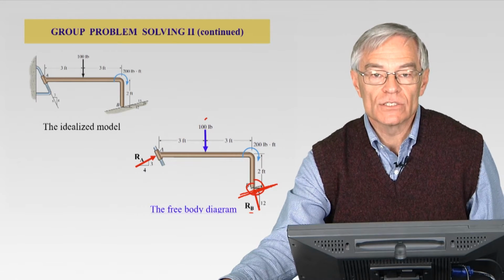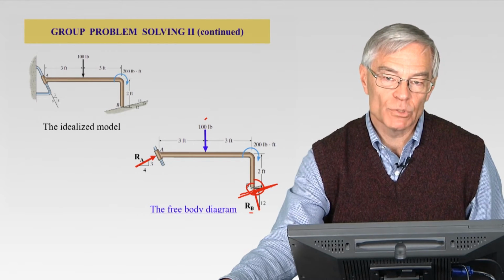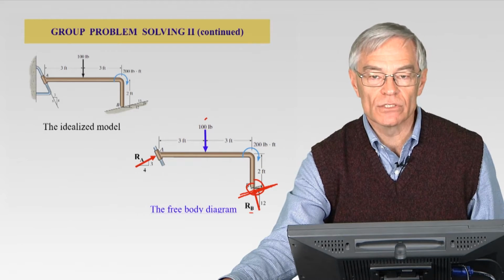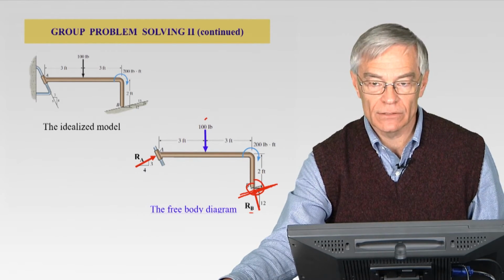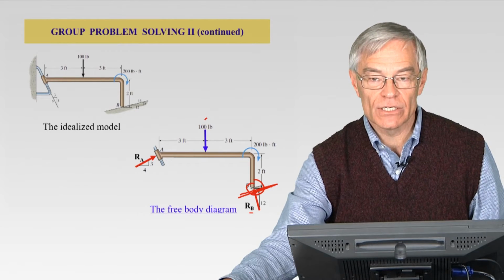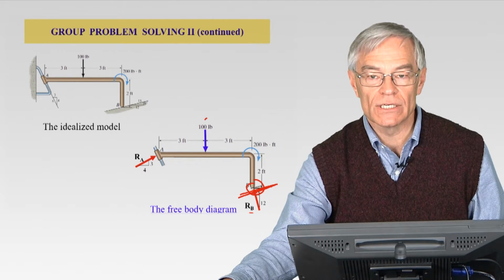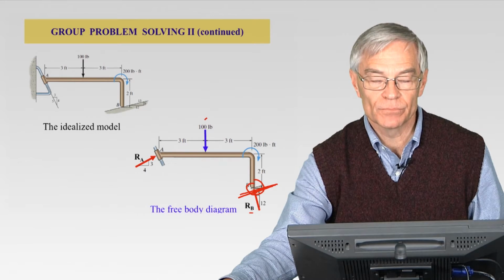Keep in mind that with these supports, you may think, well, why isn't there a moment, either in this one or the previous one? Why are there no moments acting on this thing? Again, it's because these supports don't necessarily inhibit a rotation. All right?